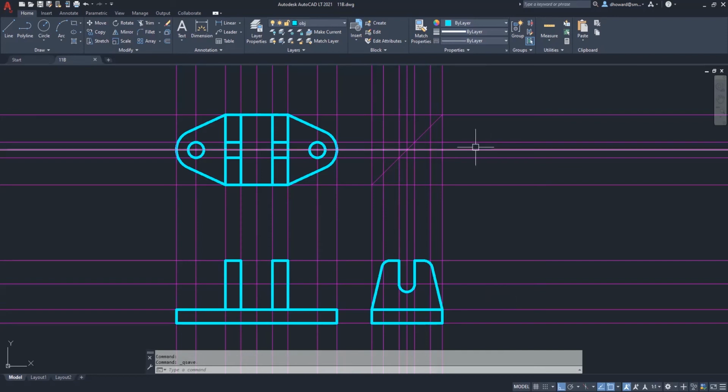I think we will start with this right side view. So that hole right there is visible in the right side view. Here it is. And its hidden lines are going to be there and there, and its center line, of course, will be in the middle. This object is symmetrical in both directions, interestingly. It's symmetrical all the way this way. It's symmetrical all the way this way. And we should note that. Remember, center lines go beyond the object a 1/4 of an inch.